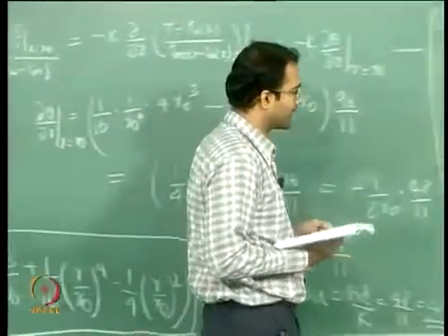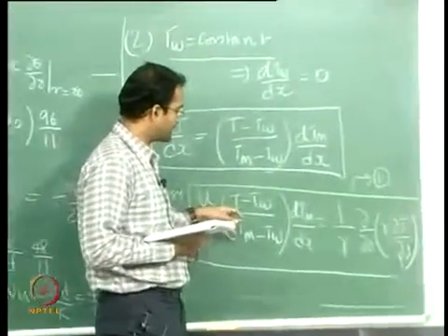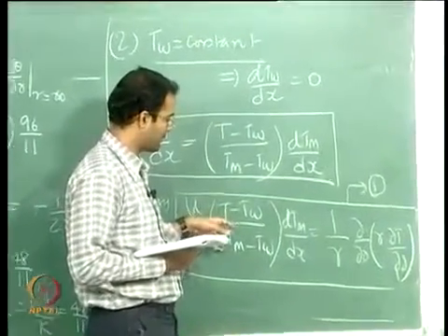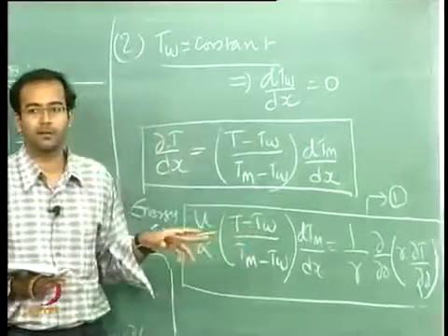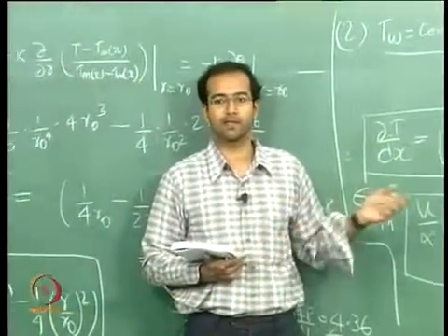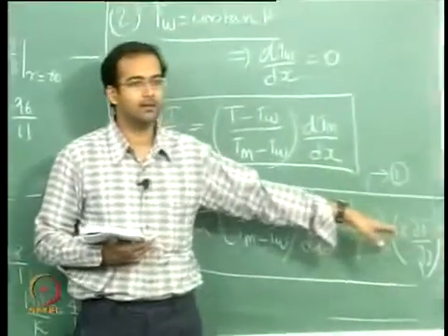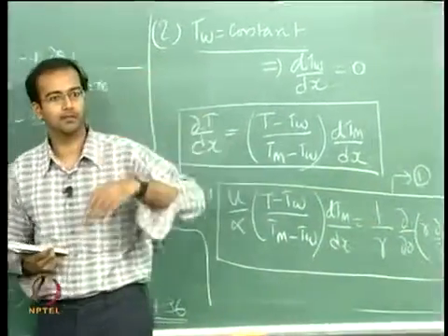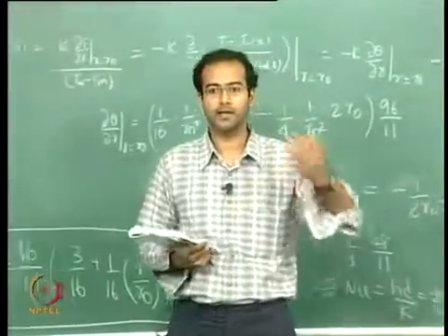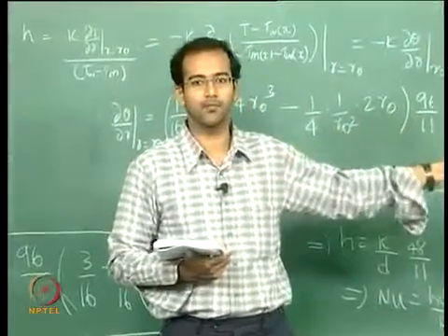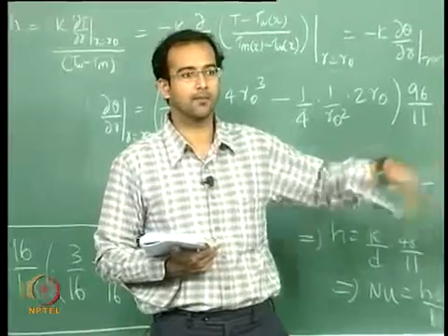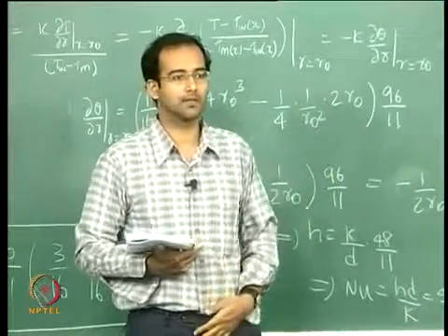So one way of doing it is you can guess some value of temperature profile, preferably from the earlier constant heat flux case, and substitute it as a first guess, and then you can integrate it along the radial direction, okay, and again get a new temperature profile and again keep putting it on the left hand side and keep doing it until you reach a converged solution, okay.